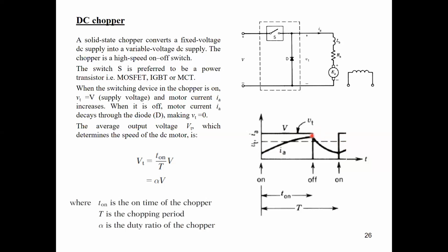And during the off mode, which means the freewheeling diode is going to work, the current will be discharged in the machine resistance. The machine inductance has stored energy, and it will be dissipated in the equivalent resistance of the machine winding itself by using the freewheeling diode. So the current will be discharged to return to the same value as the beginning current, which is called I minimum. So at steady state, the current is going to move between I minimum and I maximum for all of the time.